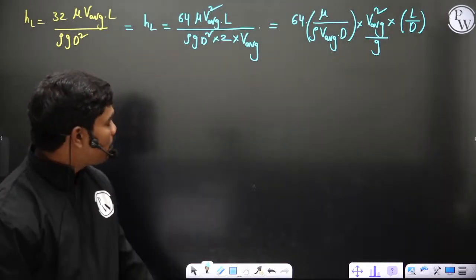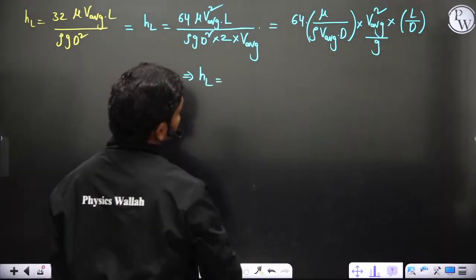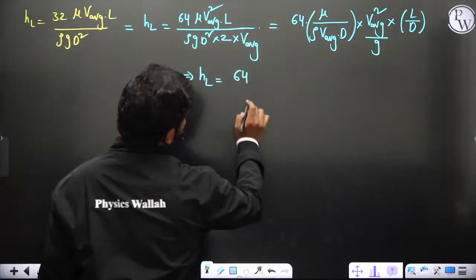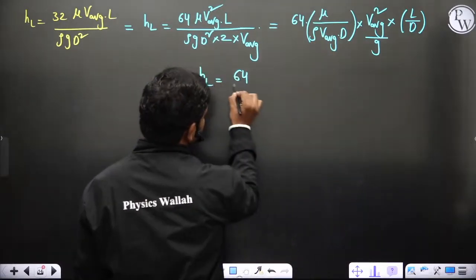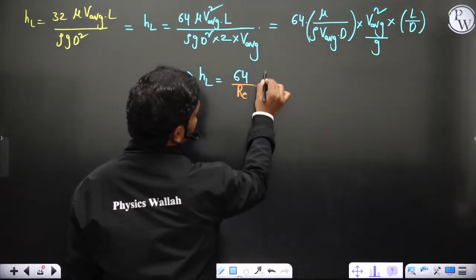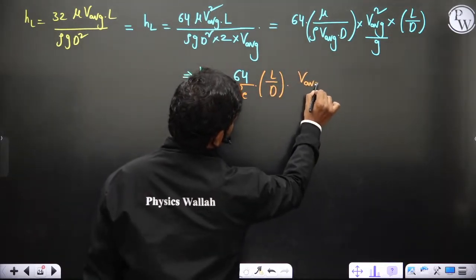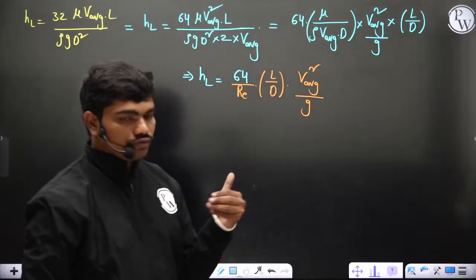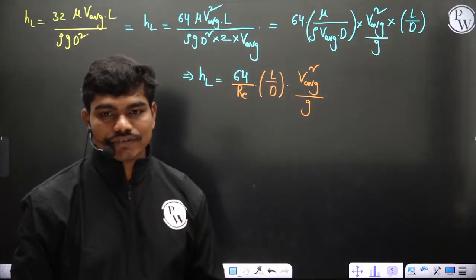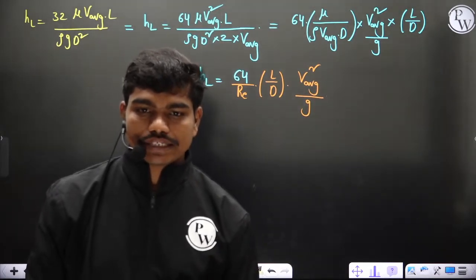Hi Dharmendra. So if you solve this here, HL is equal to 64, then clearly this combination, from your knowledge, is the Reynolds number in the denominator, into L by d into V average square by g. Why I have adjusted this formula intentionally is, if time permits, could you give physical intuition of body force and forces in surfaces and how they are considered and neglected?